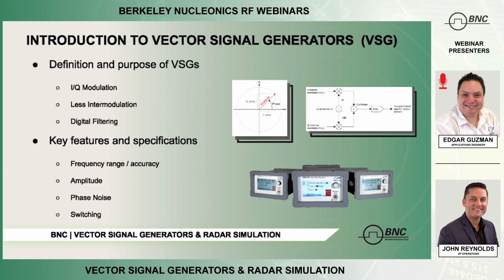Our particular vector signal generator is a digital vector signal generator. So you can see the image all the way on the right. It shows the I and Q signals coming in and being mixed with our quadrature LO signal. And quadrature just means we have two signals, usually sine waves, one at a 0 phase and the other one at 90 phase. So they're in quadrature with each other. So we take our I and Q signals, and we mix them together in a combiner. And then that goes through a digital analog converter, and from that point it's upscaled and then output through our RF circuitry.